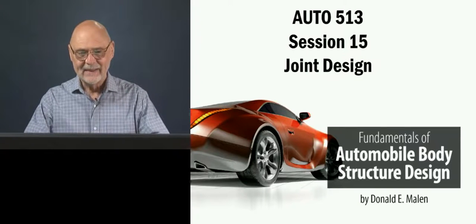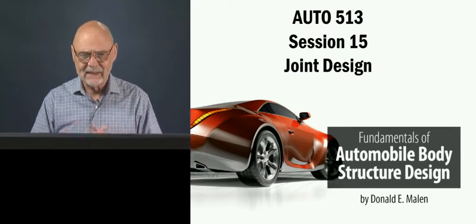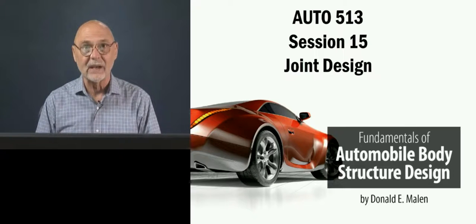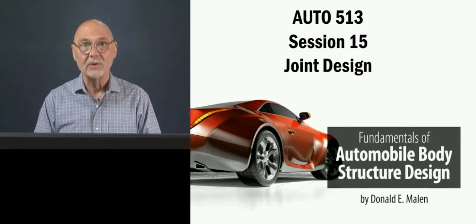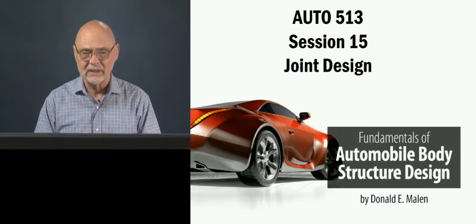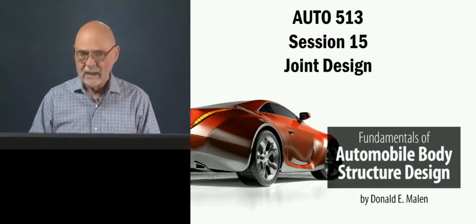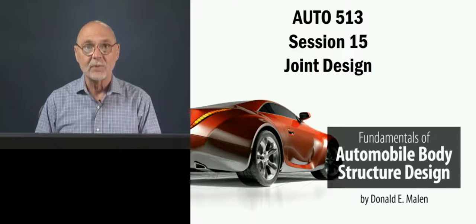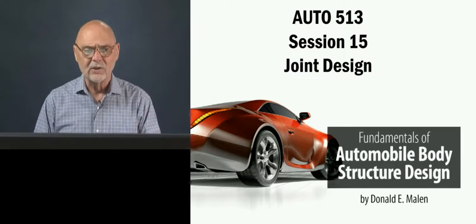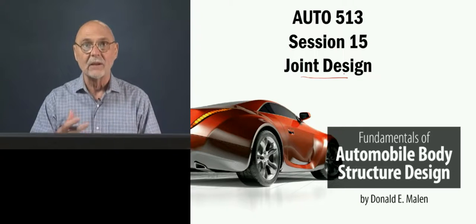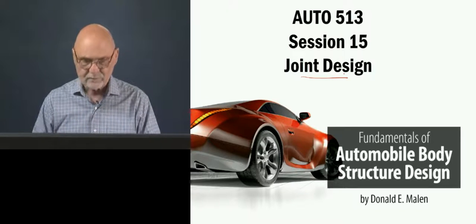Hello everyone, session 15 today, and we're going to be talking about joint design. If you remember, last time we emphasized how important joint stiffness was in the performance of the side frame, and we quantified joint performance by a single number, the joint stiffness. Now we're going to look at what design elements make up a good joint.